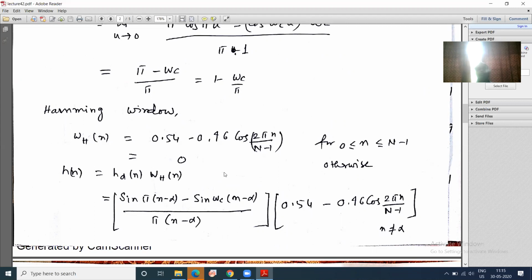So essentially, you have a gradual rise from stop band to pass band, or pass band to stop band, not sharp. Now, which one is better? If the cutoff is sharp, this is the best. Therefore, in different kinds of windows, it is observed that a different slope is observed in the passband to stop band transition or stop band to passband transition.